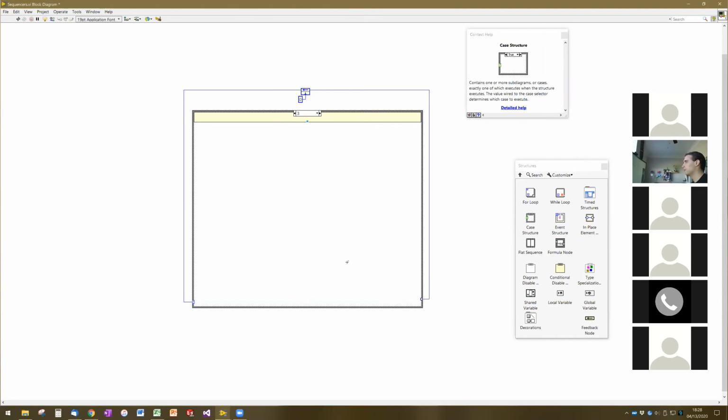The rest of the structure remains the same for all of the steps in the sequence, except for the last step, where theoretically you just wouldn't have an advance structure. You would just freeze the sequencer at that last step, assuming that your sequencer doesn't reset. Like if this was a climb sequencer, you'd have it freeze here. For other sequencers, you may want to be able to reset the sequencer and go back to state 0. That is application dependent.